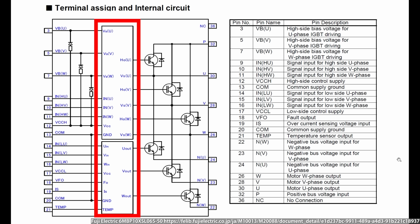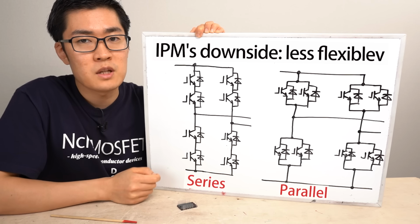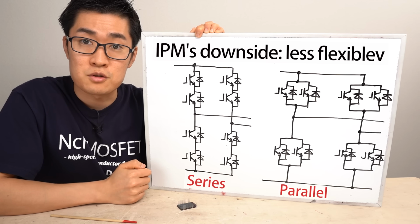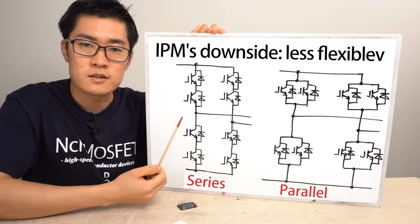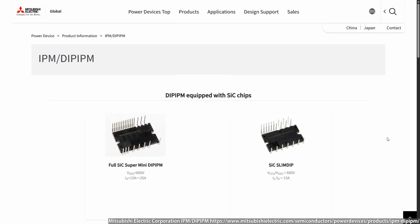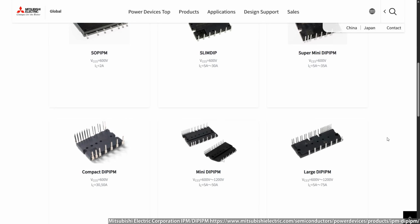Since each IPM has its own drive and protection circuits built in, there can be timing differences during switching or protection events. As a result, the current or voltage may become unevenly distributed and concentrate in a single IPM, which can eventually lead to device failure. For this reason, we don't connect IPMs in series or in parallel. Instead, we choose an IPM from the lineup offered by different manufacturers based on the application.